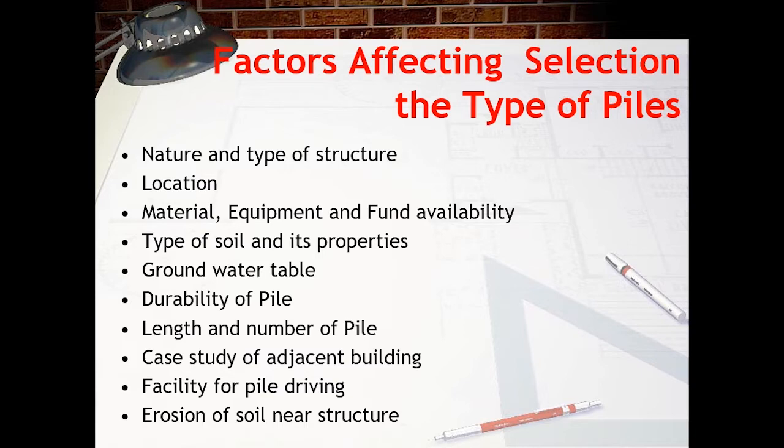Before the actual construction begins, pile load tests must be conducted to verify the design values. The foundation design must be revised according to the test result. The factors that govern the selection of piles are the nature and the type of structure.